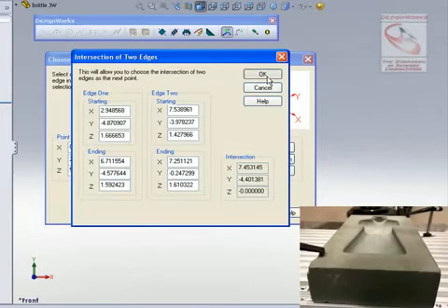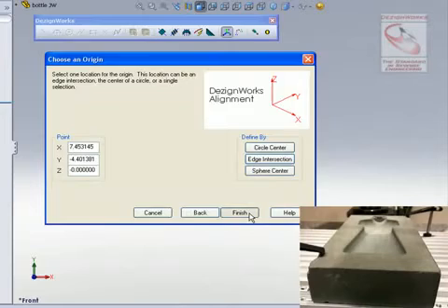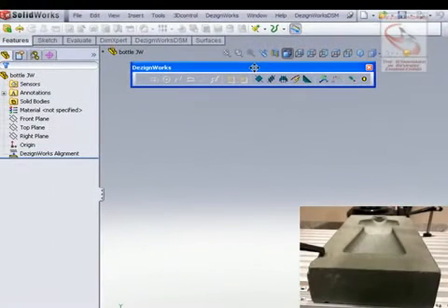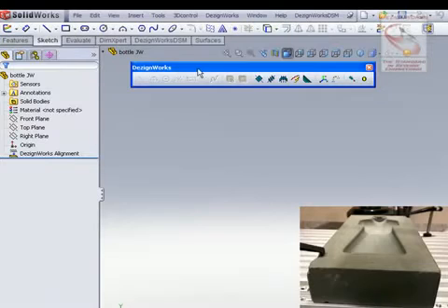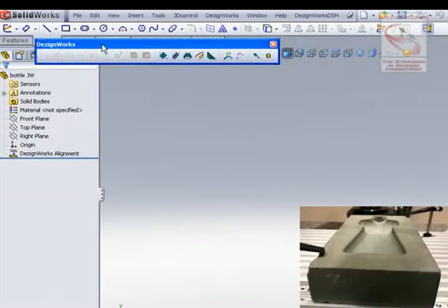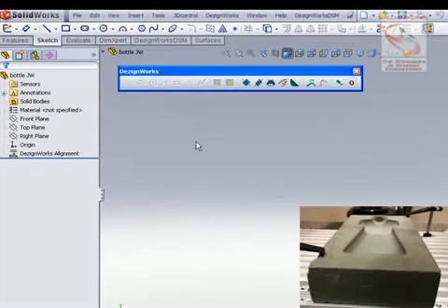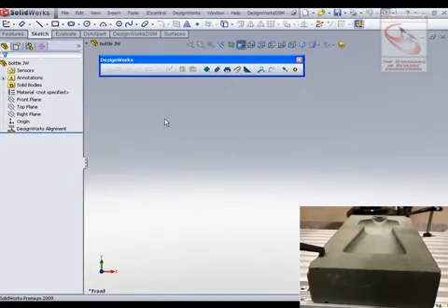What you'll notice is, if you're already a SolidWorks user, that you already know how to use DezignWorks. Because of our in-depth integration, the toolbar matches your sketch toolbar. You can also digitize interactively, sketching with the SolidWorks tools and digitizing at the same time. So let's go ahead and use the DezignWorks tool and outline our part. Notice the alignment's been stored in the part for you.